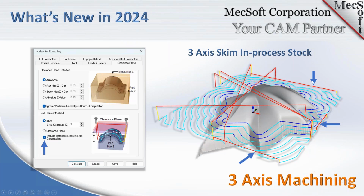So if you look at the arrows over here, you'll see that in the areas where the tool had to traverse above the part, it applied the skim clearance to the highest position on the part. But if it didn't have to span over the part, it calculated the skim clearance based on the cut level.